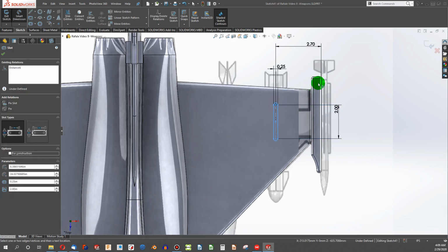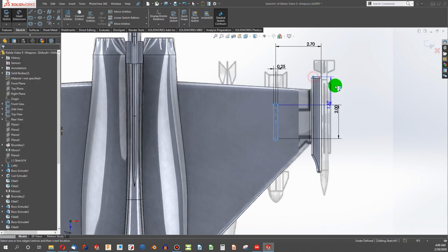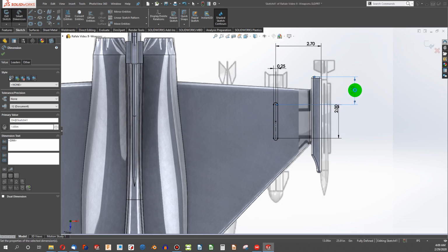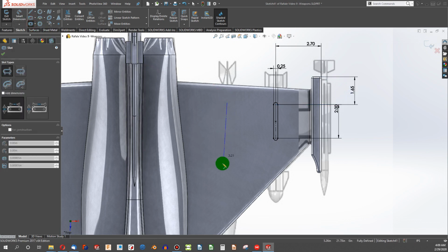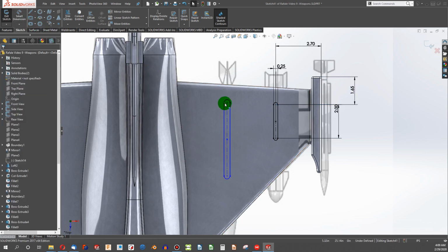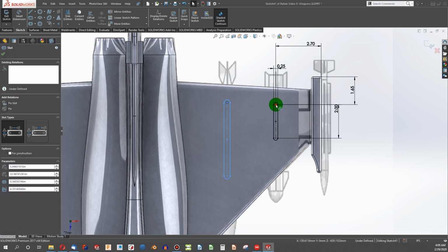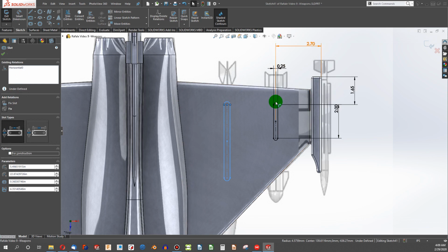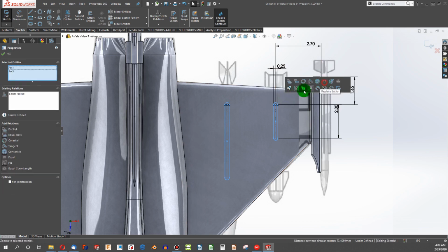And I like that position on the wing. Again, using an arbitrary edge, which in CAD practices is probably not the best, but again, we're not even fully constraining here. We're going to go 1.65. I want to do the same thing with another slot feature. I'm going to choose these two and say horizontal. I'm going to choose this arc and say equal.